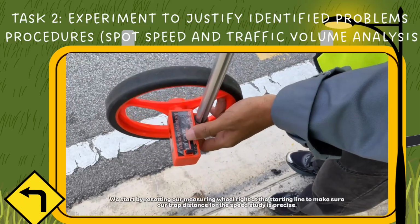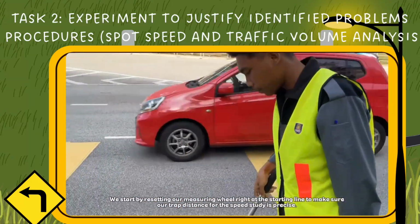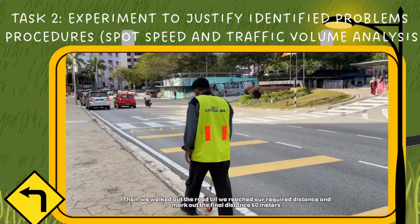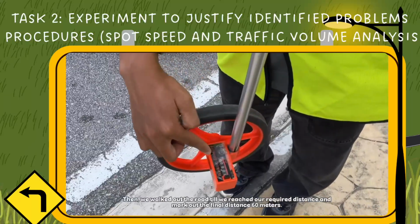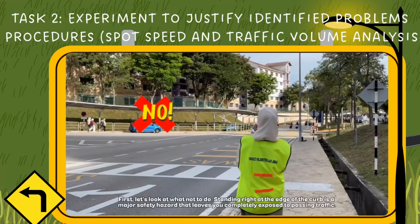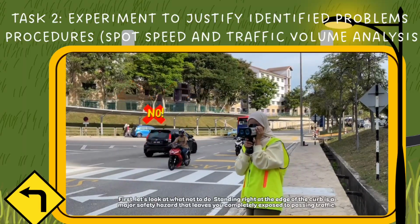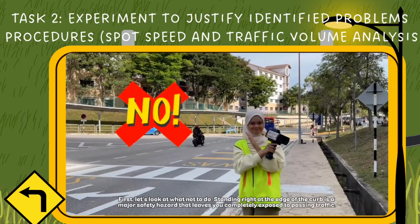We start by resetting our measuring wheel right at the starting line so that the track distance for the speed study is precise. Then we walk out along the road till we reach our required distance and mark out the final distance, 60 meters. First, let's look at what not to do. Standing right at the edge of the curb is a major safety hazard that leaves you completely exposed to passing traffic.